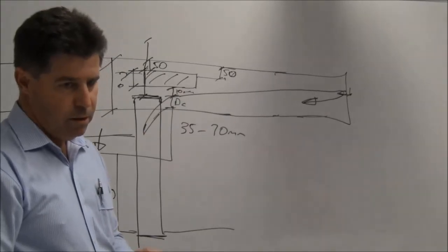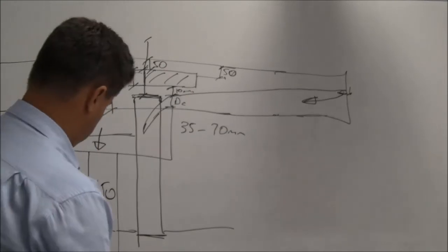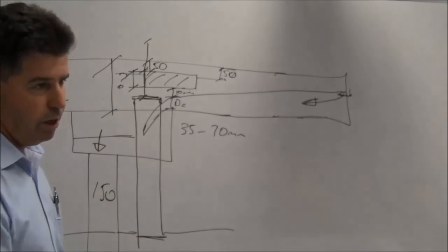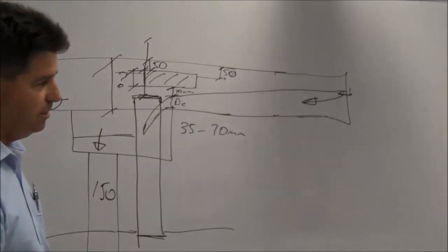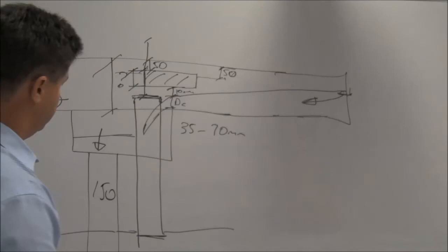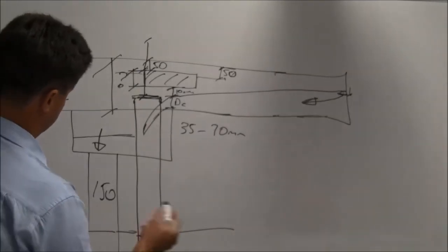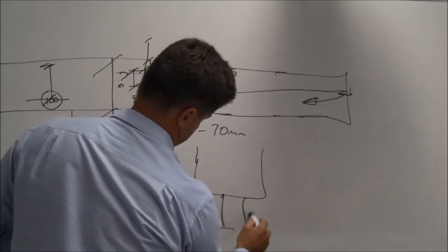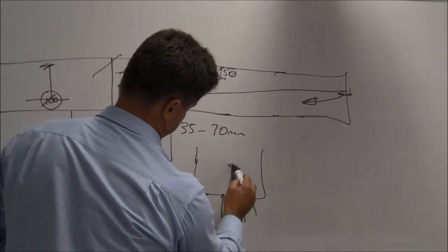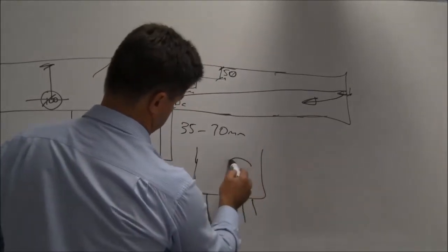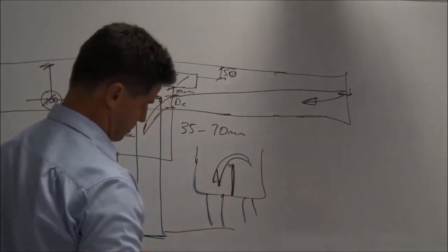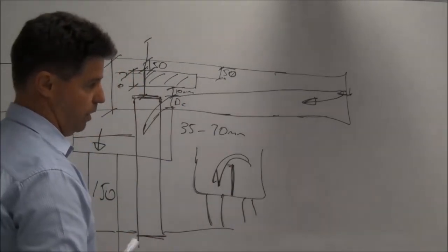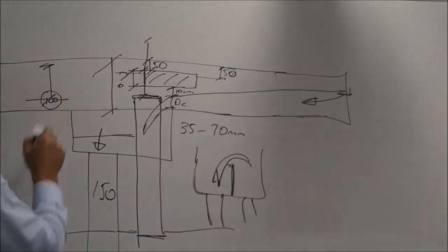Yeah, that's what I did for what I call a drop overflow. But what do you call that overflow? This overflow is just a vertical overflow. There's nothing special about it. High capacity overflows you can do in a sump where you have an outlet here and an outlet here, and you might have a weir that sits in between the two. Oh, okay, so that is overflowing over the top. There's a whole heap of different ways you can do overflows. It's not any one particular way.